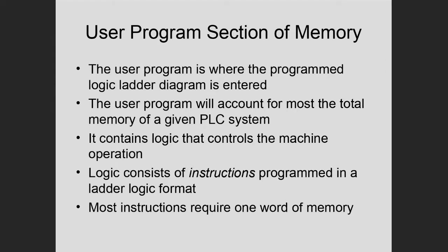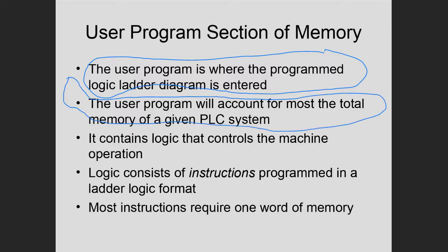So it's where your ladder is kept. And it also says here that this will account for most of the memory of the PLC. So if you have a really, really long program, most of the memory, the kilobytes, whatever number of kilobytes, most of them will be used right here. It says most instructions require 1 word of memory.